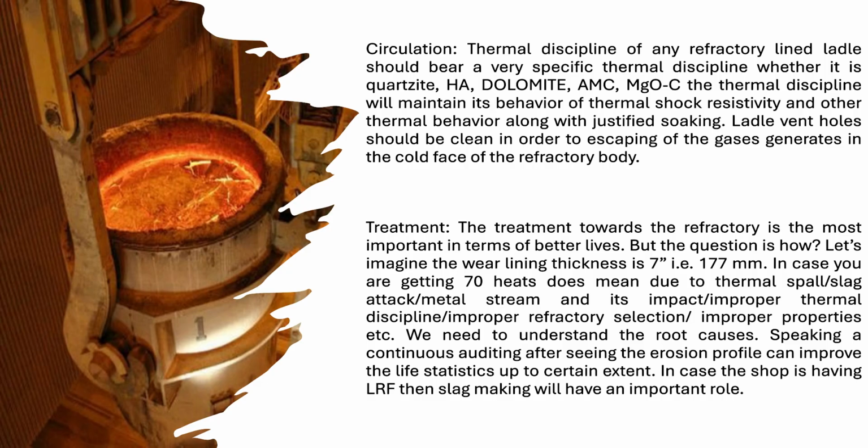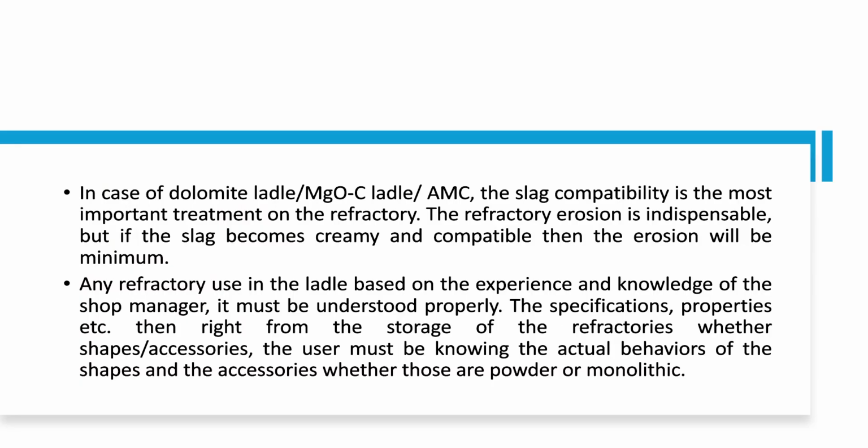Continuous auditing after seeing the erosion profile can improve the life statistics up to a certain extent. In case the shop has an LRF, then slag making will have an important role. In the case of dolomite ladle, magnesia carbon ladle, or AMC, slag compatibility is the most important treatment for the refractory. The refractory erosion is indispensable, but if the slag becomes creamy and compatible, then the erosion will be minimum.